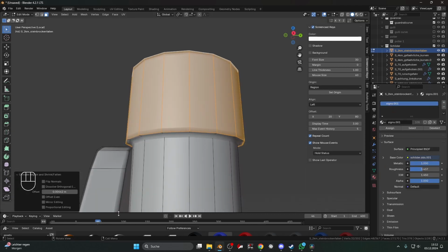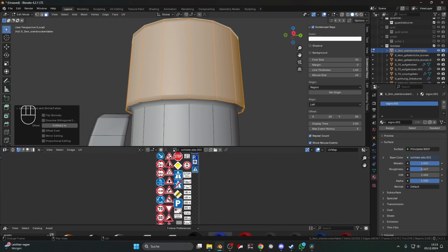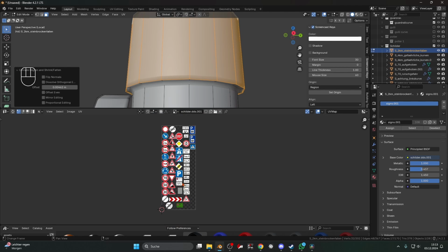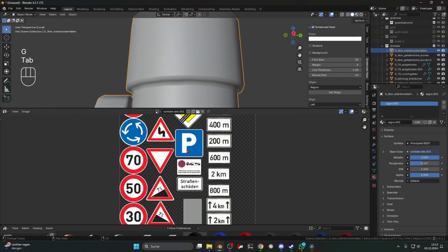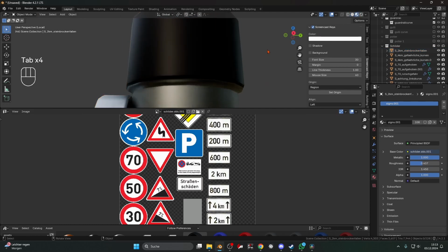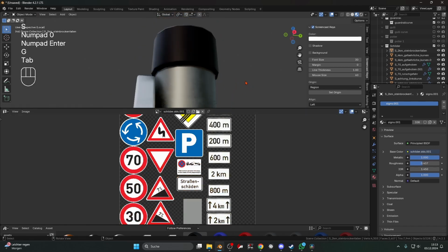And we go to the UV maps. I do have all of these together, and we will get to this part really soon. I will just unwrap this, scale to 0, and put this on a black patch. Unwrap, scale 0, somewhere black.